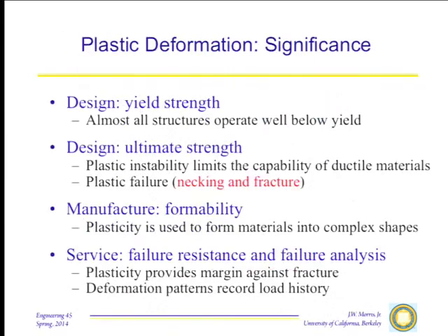Okay, plastic deformation is that second regime. In what sense is it important in engineering? Well, from the perspective of design, virtually every engineering device is designed so that we don't have plastic deformation. You don't want the dimensions of your devices changing while they're in operation, your automobiles or your engines or whatever they are. So the yield strength must be known and understood, because the design limit is stated with respect to the yield strength in virtually every design code there is.